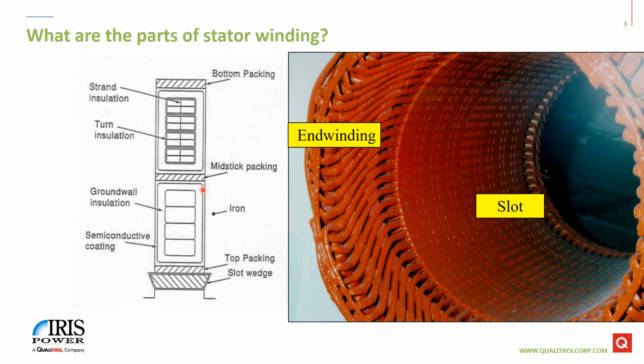And so our focus here is going to be on this coating because, because of the epoxy content, it's an organic material. It's just like a human being. It will gradually age over the years and become less effective at being a good electrical insulation. And really and truly, what we're doing with online PD or offline PD is detecting that aging, okay? Because PD is quite often a symptom of the deterioration of the stator winding insulation system.